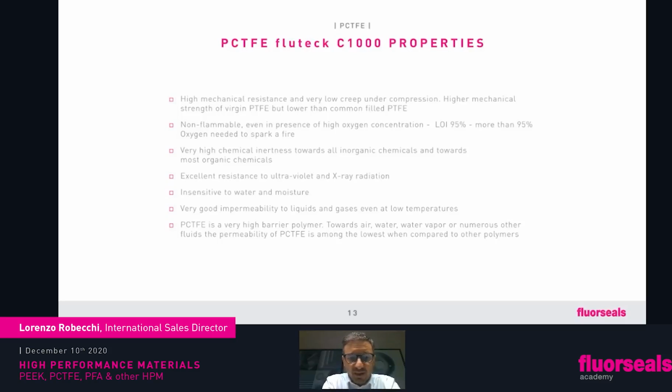PCTFE does not spark up, okay? Chemical resistance, as many fluoropolymers, okay? We know it doesn't go up to PTFE, so you may check some situations, but generally speaking, very good. Resistant to ultraviolet, water, moisture, and permeability. PCTFE is a very good barrier. We're going to look later at PFA, and I'm not sure you want to use PCTFE because it's a good barrier, unless you're looking at cryogenic application.